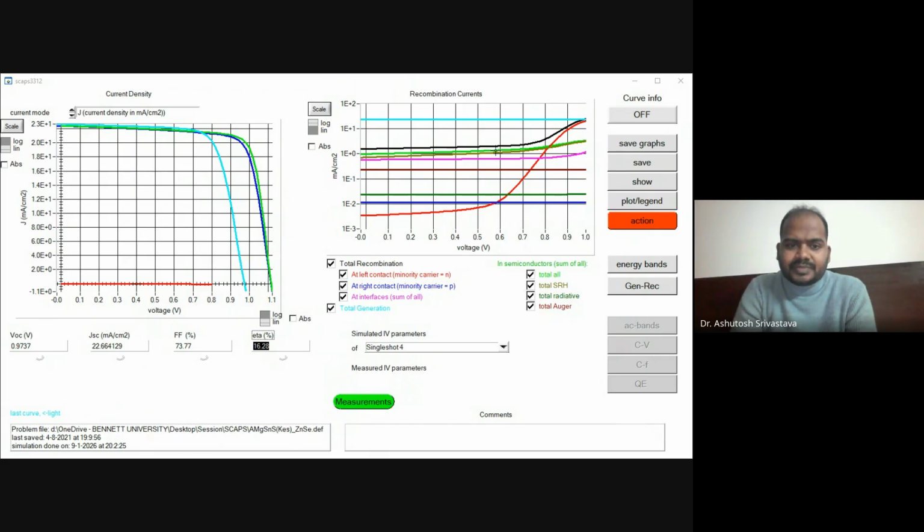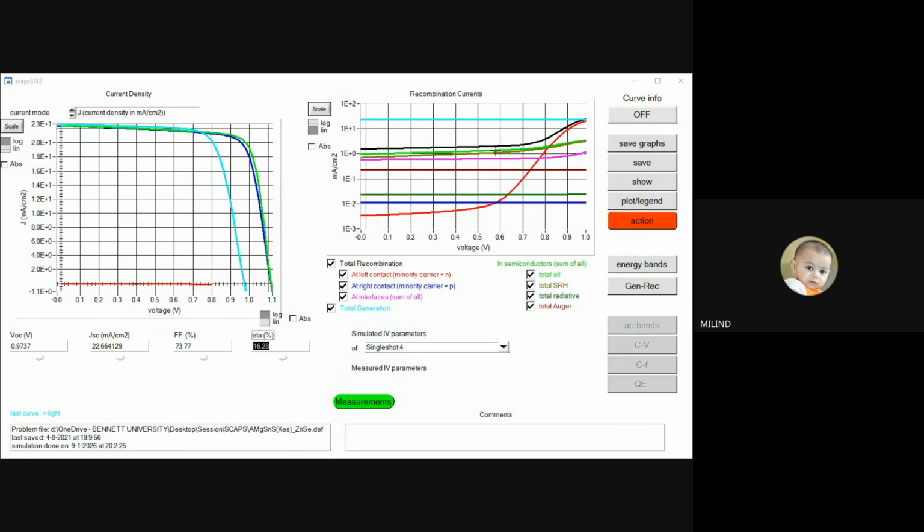We can change the values one by one. Let's say we first focus on changing the thickness. When we are changing the thickness, we focus on how this changed thickness will affect my device. So I'll change my thickness, let's say starting from 1 micron up to 1.5, 2, 2.5, whatsoever. Let's say we took 4 or 5 such simulations, and eventually we obtained that at 2 microns my system is working well. So now I'll fix that value to 2, and then